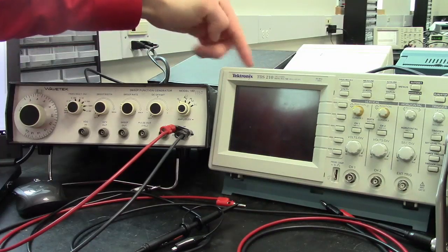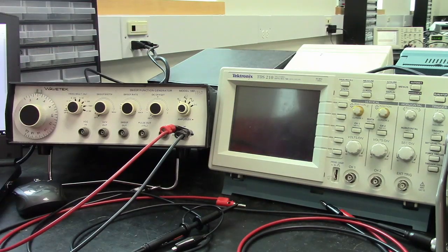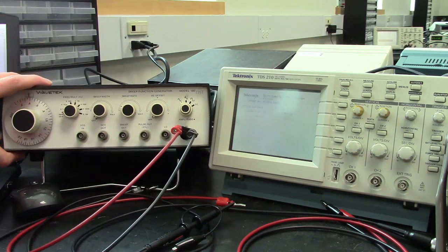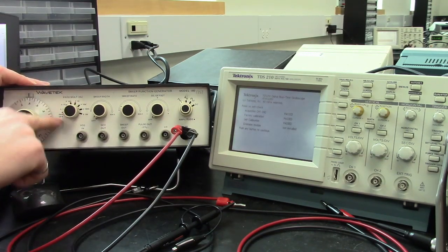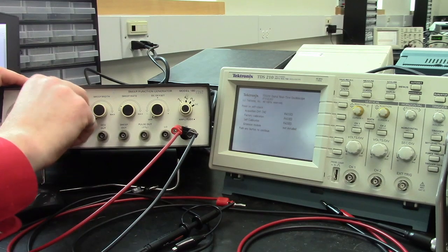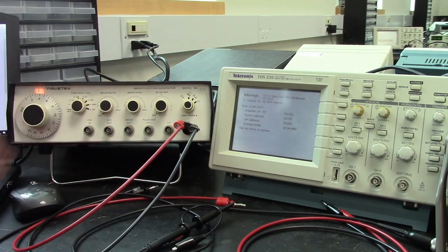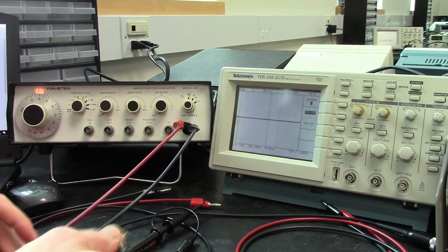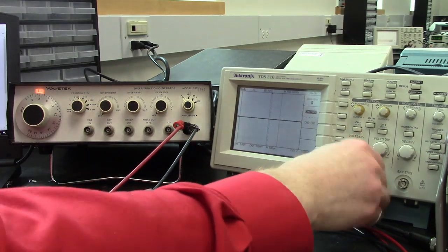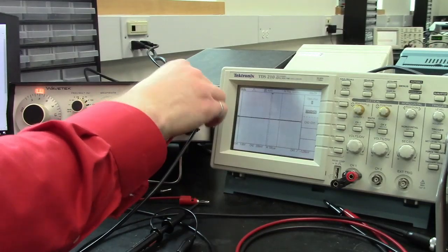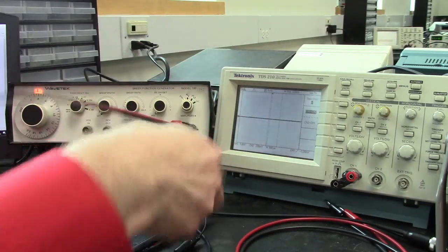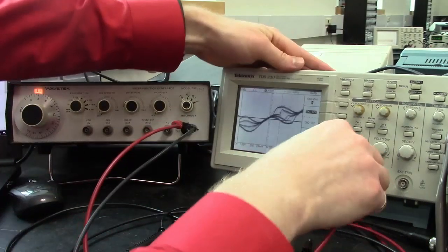So, to turn on the scope, the power button is up here. We're going to wait for that to fire up. To turn on the function generator, you use the frequency multiplier here. So on the bottom left, it's power off, and we can turn this up to go to the right frequency. So, as the scope powers up, first thing we can do is apply the signal from the function generator to the scope and try to look at it.